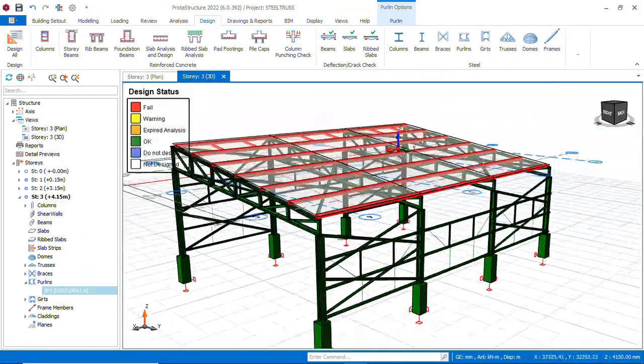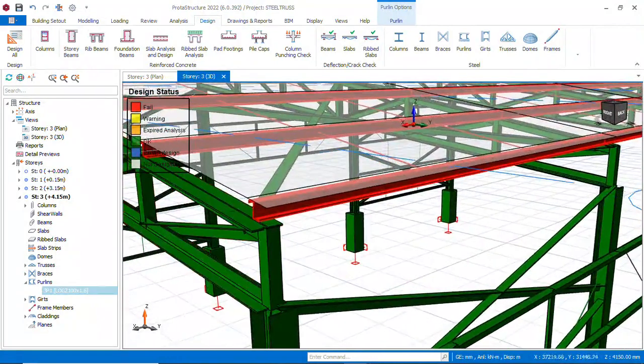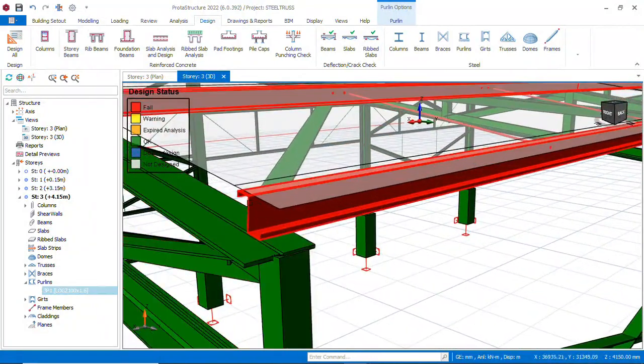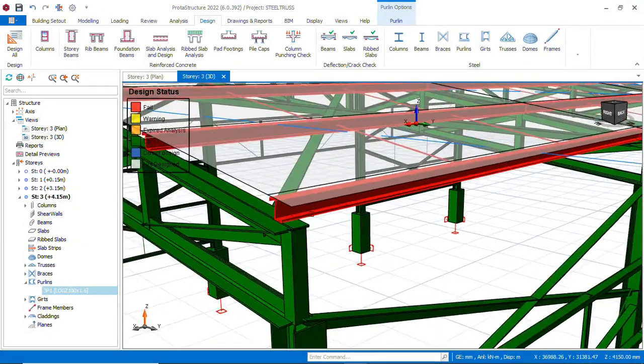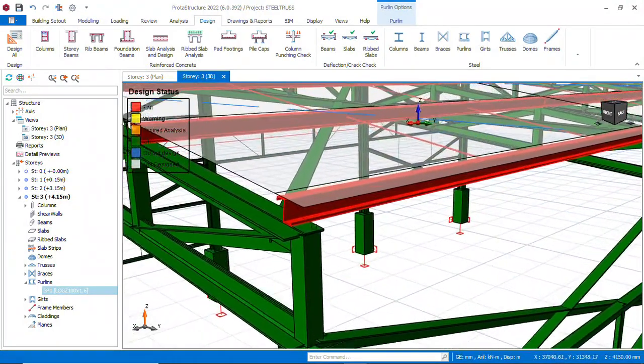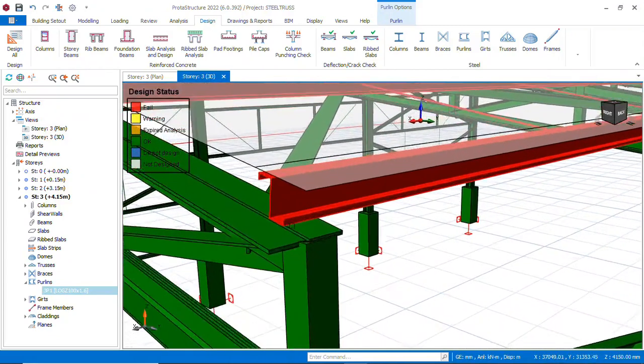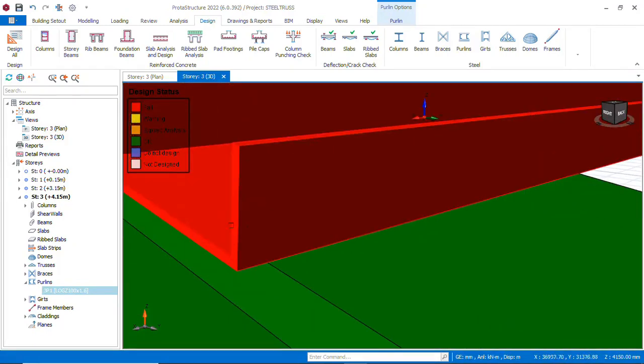Or what you can do here is either you can remove this and use a bigger section of your purlin. We increase the thickness of your purlin. This thickness, increase it from here to here.